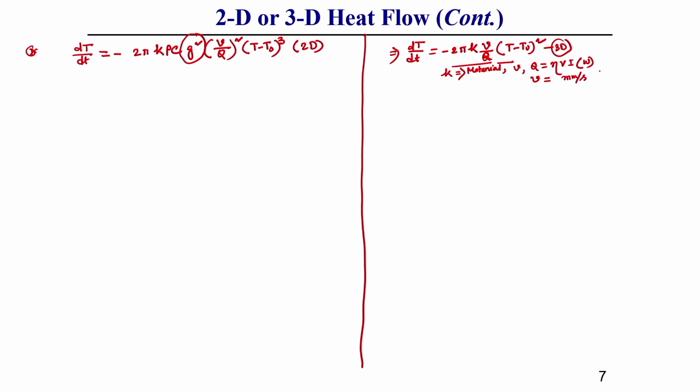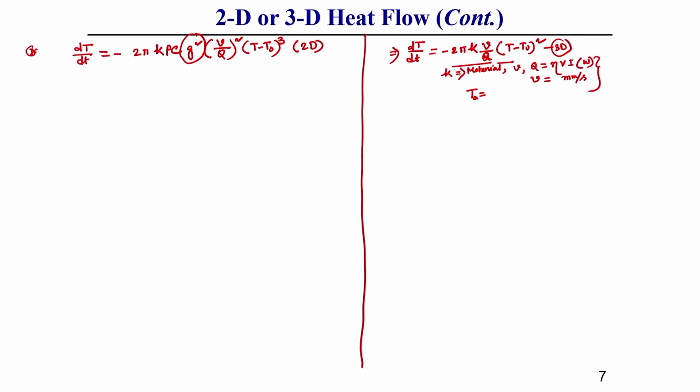If these are constant for a welding process, and another thing, if your actual temperature T and T0 are also fixed, let us say for a particular temperature T, the actual temperature, generally for cooling rate calculation for a welded specimen, this T actual, which I am writing as T A, is generally considered as the nose temperature.